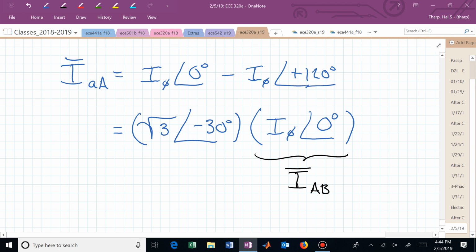But now what do we have coming up? Now we have an ability, by just analyzing a single phase circuit, to find different quantities. We could find the line voltage from just knowing the phase voltage. Or if somebody gives you a line current and says this is really a delta connected load, you can now find the phase current flowing in that particular load's impedance.